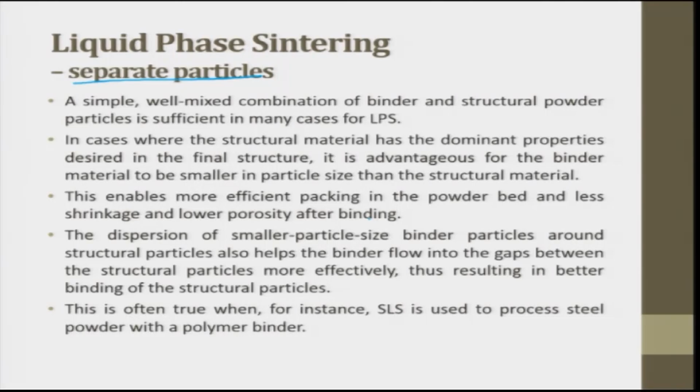So this enables more efficient packing because the binder size is very small, and less shrinkage, because the particle which is going to melt and flow only shrinks later. So now the shrinking has gone very low, and the porosity after binding is lower, because wherever there is a pore, it will get filled up. The dispersion of the smaller binder particles around the structural particle also helps the binder flow into the gap between the structural particles more efficiently, thus resulting in a better binding of structural parts.